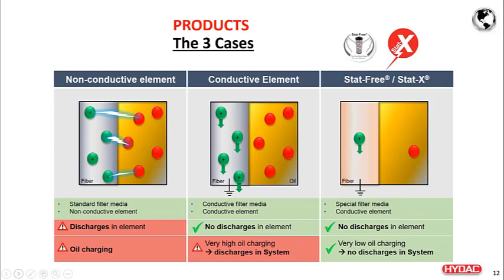Now, in the conductive element, which is what is normally utilized by most of HYDAC's competitors, those conductive elements are typically made with either carbon fibers or metal fibers engraved into the glass fibers. There are pros and cons. The pro is, yes, you're eliminating charge at the filter, but the charge is still being generated when the oil is passing through the filter element.